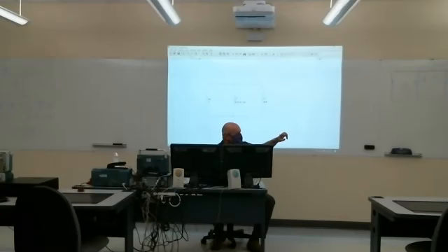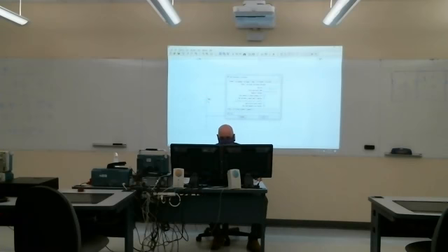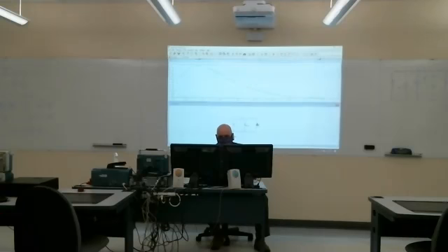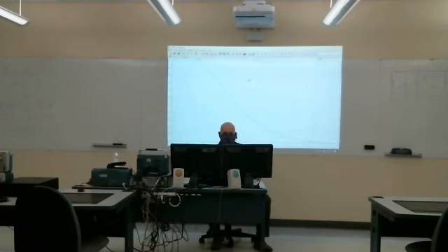So now if we run this, according to that, it's a decaying sinusoid, and the time constant's about half a second. So if I run it out to about 3 seconds, it should have essentially decayed away. So we can do this with a stop time of about 3 seconds. Here, you have to check this skip initial operating point solution. That throws in this UIC, which is funny the way it's worded, but that means actually use the initial conditions. And so this is what I get out for the LTspice inductor current.